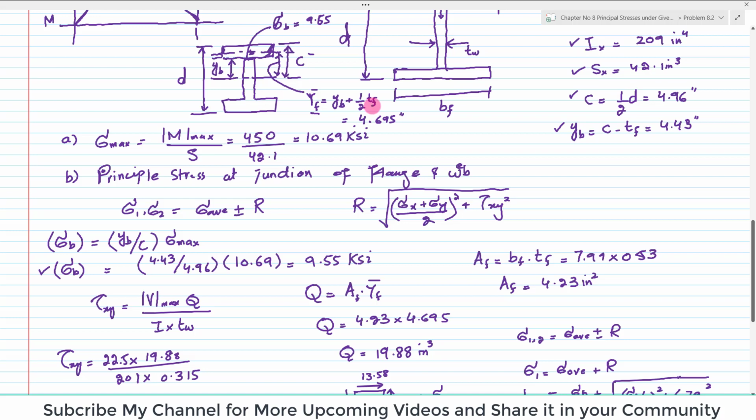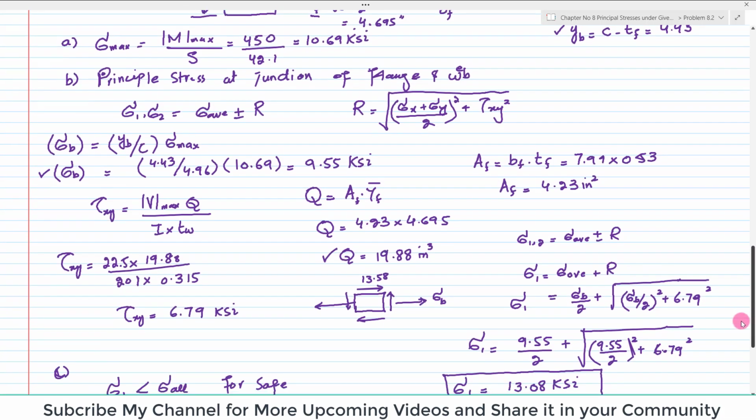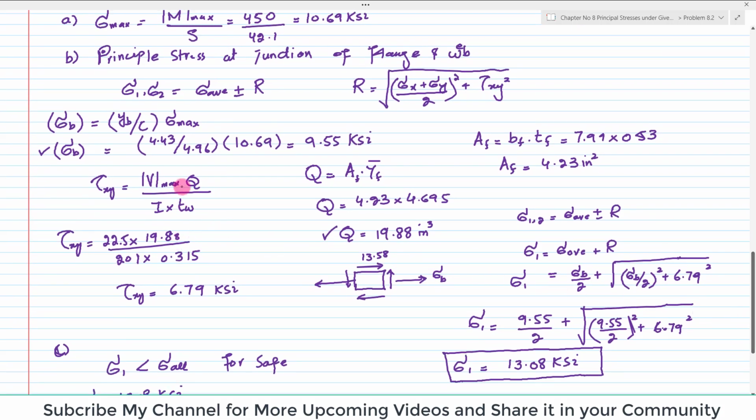Again, it is written. So when you put the values of TF and YB, you will get YF. Now you have YF and AF, you can multiply them, so you will get the first moment of area about the neutral axis. Now put the values of Q, V, I and TW in this formula, so you will get the shear stress at the junction point.